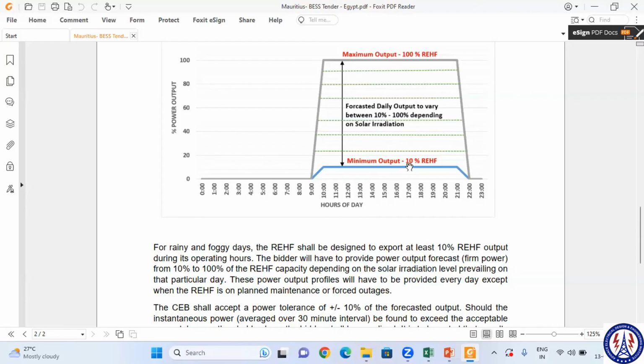Can you please repeat why you find this odd? See, if you observe, 5 hours to operate from the BESS, right? This is clear now. 5 hours we need to operate because solar won't generate much within this time. You're saying just to consider 40 megawatt as a total load, right? But I am thinking the 40 would not be their total load. The load would be a little lesser, it might be up to 10 megawatt or 20 megawatt somewhere, not 40.